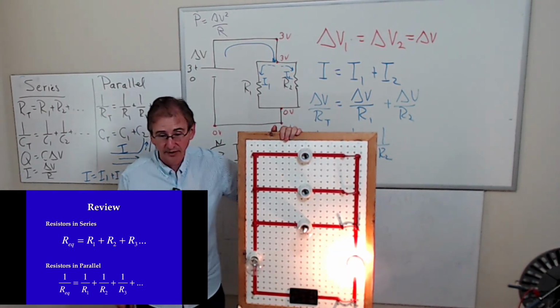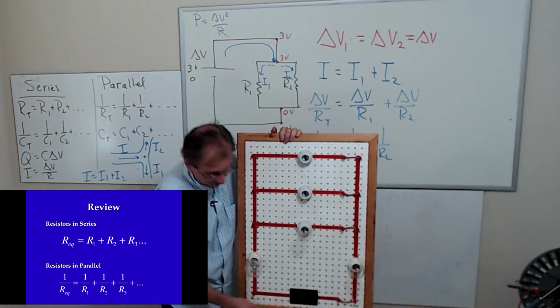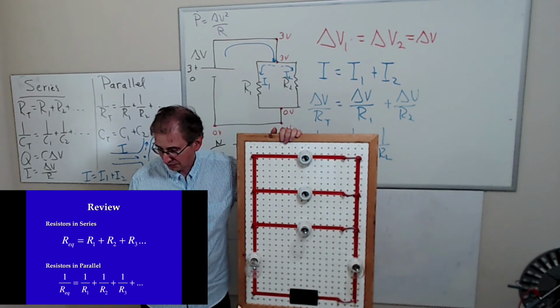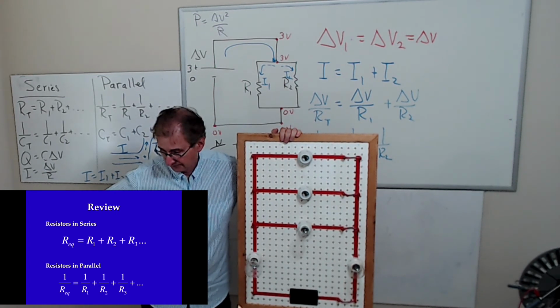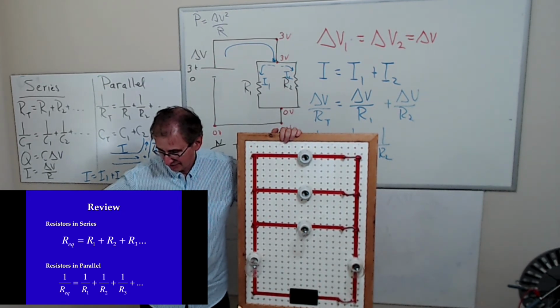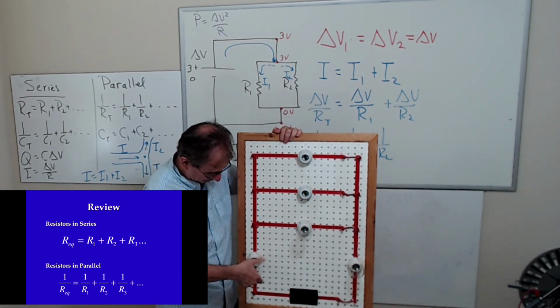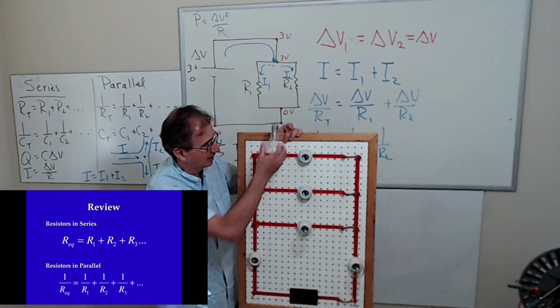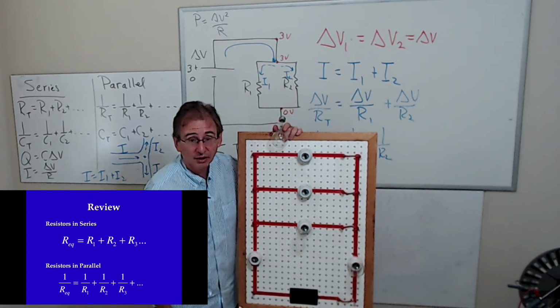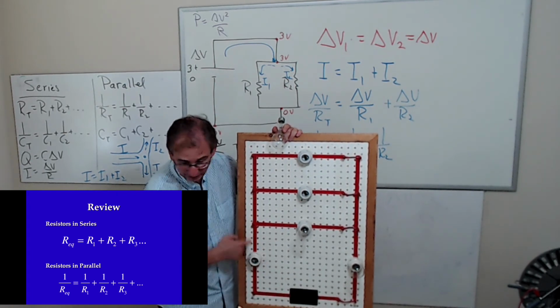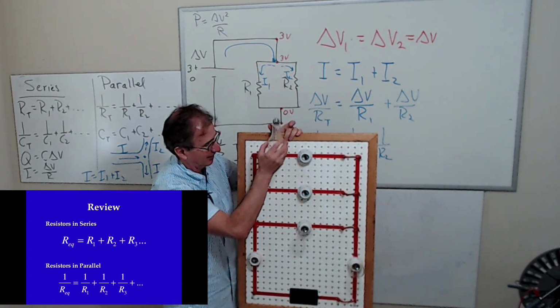Doesn't matter. So another question that might come up is, oh, the 200 watt bulb doesn't work. What's wrong with saying that? Yeah, none of them works. If I take this guy out, it's the same thing as if it was dead. None of them would work. I'd actually have to bypass it to get it to work. I'd have to short this point out to get it to work. Now, all right, now I'm going to put them in parallel.